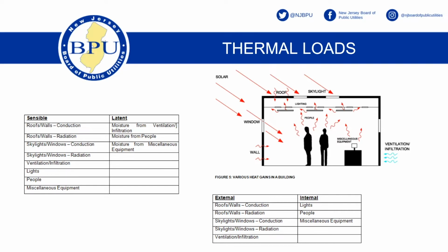these external loads here from the sun, from just the air being cold and coming in from the ventilation and infiltration coming from the outside. In addition to the lighting that we talked about, all these computers we have, and over in the computing places, there's a lot of heat that you have to get rid of one way or another. And you'll see when we get to the energy audit later today, a situation where they have excess heat, but in some cases, they turn the central system off and they have a local Liebert unit or something that'll provide heating and cooling for computers.